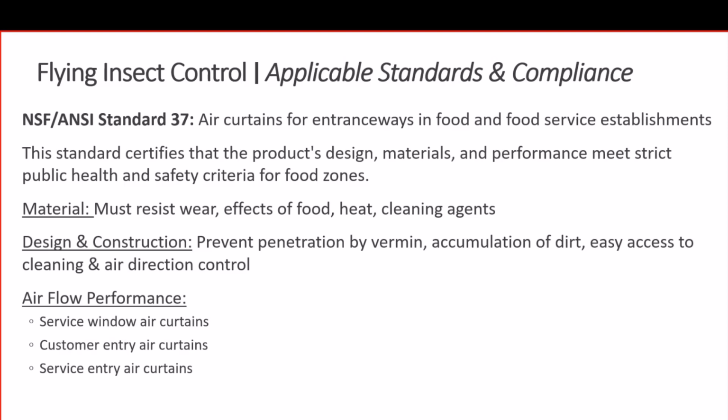To my knowledge, NSF and ANSI 37 standards are one of the only guidelines or standards that are applicable in North America. These standards not only talk about the airflow requirements, but they also talk about other design criteria such as the type of material and coating that we have to use. The material should be wear resistant. It should be able to withstand the effect of food and some common cleaning agents. And from a design and construction standpoint, there are a whole bunch of criteria.